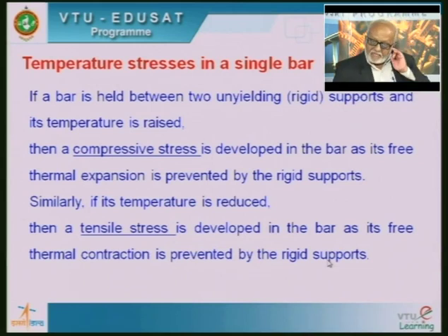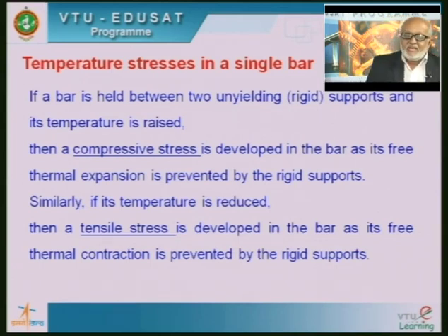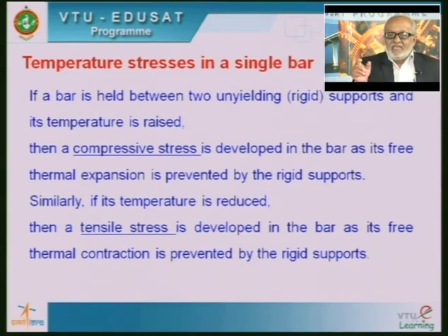So this is a very interesting concept. You will have a lot of applications in engineering. Sometimes even in buildings, when we are designing it, if the length of the building is more, or if the buildings are highly angular in nature, like it is not in one line, it is all going in different angles, then to see that cracks do not form, we are going to leave what are called expansion gaps, so that within that the free expansion and contraction can take place,